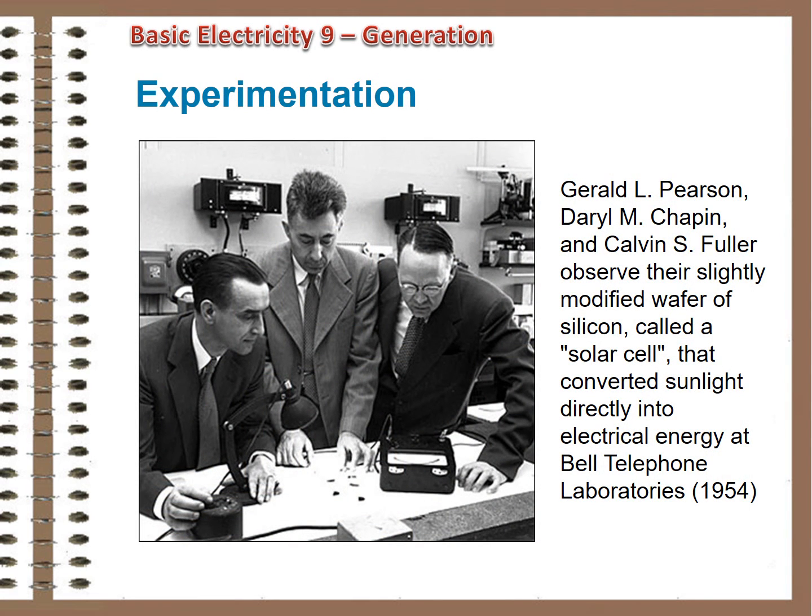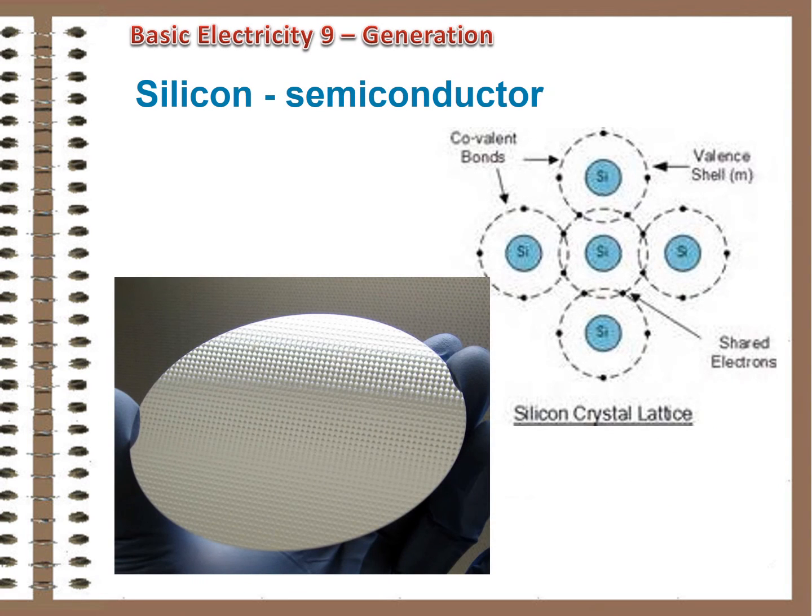How does that work? Well, in the late 19th century, it was discovered that light rays could make charge move. It took a lot of experimentation, many stops and starts, and frankly, the fear of pollution and running out of fossil fuels to really kickstart things. But now solar technology is spreading rapidly. Most solar cells are still made from layers of silicon. If you'll remember, silicon is a semiconductor, an element that normally does not conduct electricity. The 4 electrons in its outermost shell bond to other silicon atoms in a regular crystalline pattern that results in no free electrons.